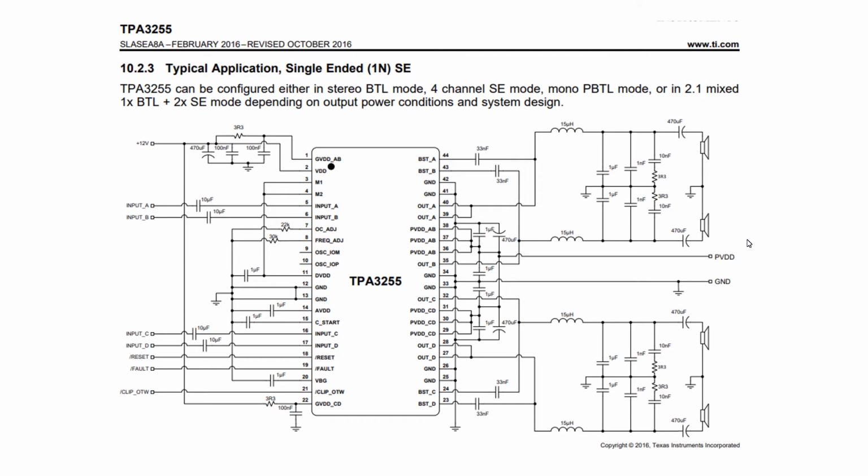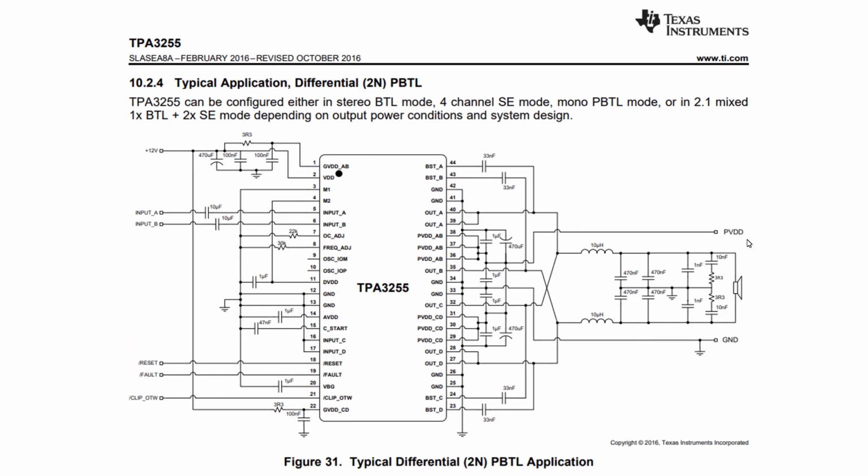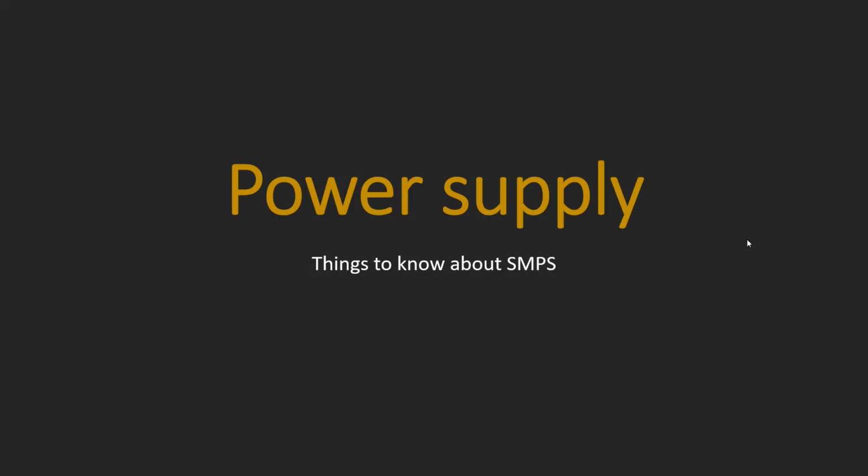4 channels configuration. You may combine 2 outputs in BTL for the woofer and 2 outputs for a mid-range and tweeter via capacitor. For mid-range and tweeter, output capacitor resistance is negligible. It may be an interesting solution for budget active 3-way high-performance speaker system. Parallel BTL, subwoofer monster of massive power. And summarizing, TPA3255 has amazing flexibility, especially in connection with DSP crossover. There are some potential for a great three-way speaker projects when the budget is critical.